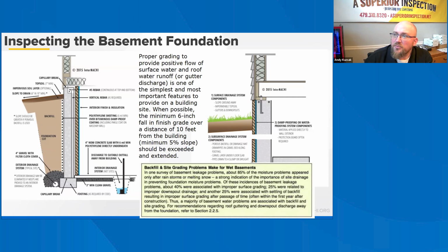The terms waterproofing and damp proofing both relate to moisture protection, but are often misapplied or incorrectly used by inspectors. Damp proofing does not provide the same degree of moisture protection as waterproofing. Model building codes typically require damp proofing of foundation walls that retain earth and enclose interior spaces below grade.